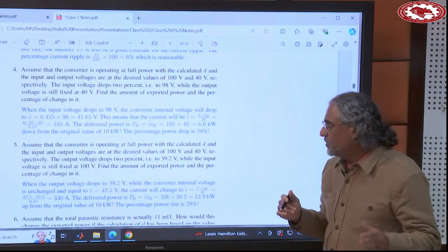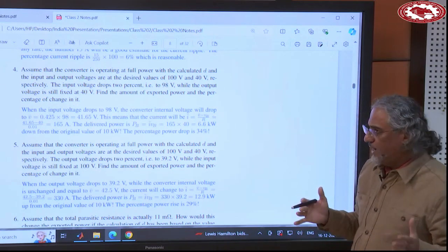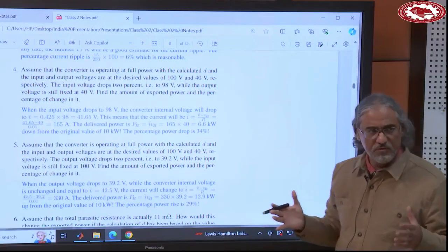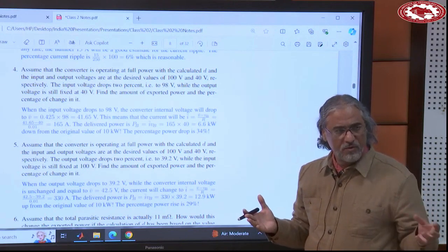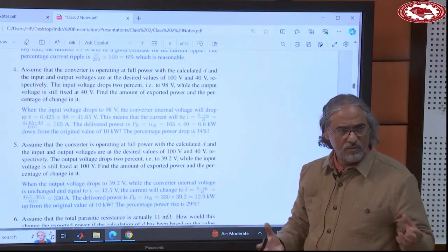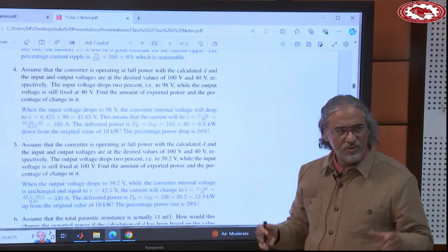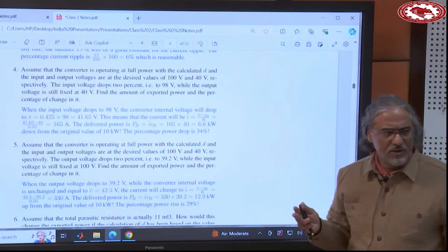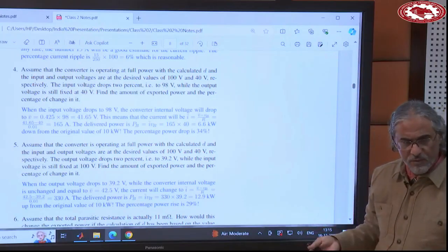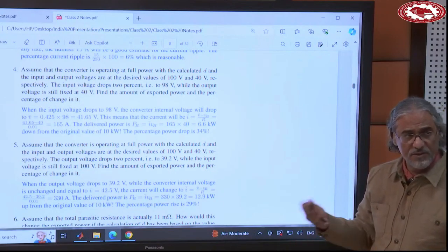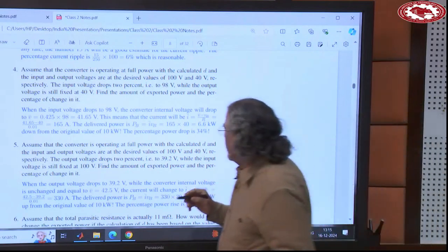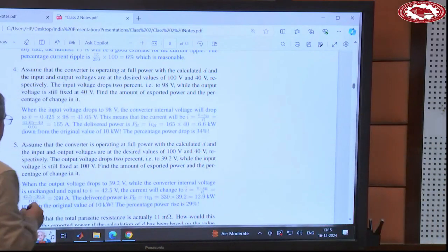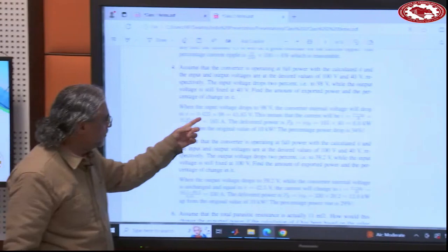And remember, these voltages, VA and VB, in practice are coming from different sources. So maybe it's on the terminal of a battery, on a load, somewhere. So when we say 100 volts, we say rated 100 volts. It could be 98. It could be 97. It could be 103, right? But you see, the duty cycle at the rated is 0.425.